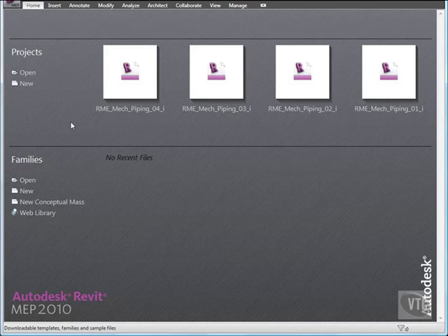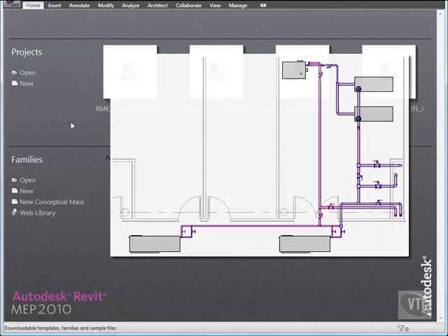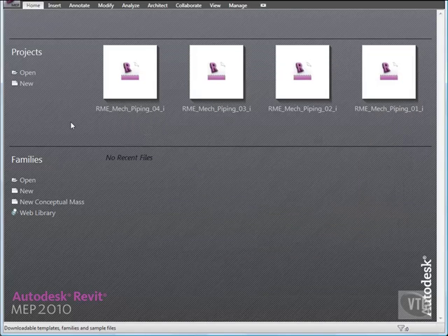In this lesson, you will add valves to model the piping for two modes, cooling mode and heating mode. You will add a bypass valve to stop the flow and direct it to the cooling tower in the cooling mode. When the valve is open, the water bypasses the cooling tower and is heated by the boiler. You will also add shut-off valves to control the flow to and from the cooling tower.